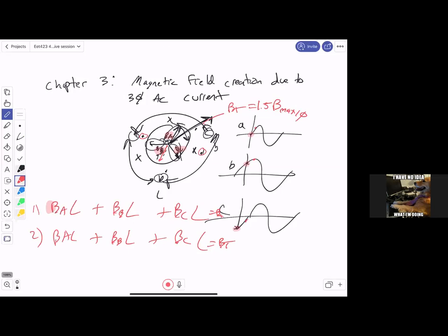Because I can't decouple whatever the device is connected to. The motor is connected to this external mechanical device, and I can't decouple it easily. Can you tell me how to wire this thing up? I see that this is 1, 2, 3, and I can see inside the machine how it goes. You would have to tell them, okay, take phase A to this point, take B to this one, and C to this one, based on the fact that you can't decouple it. So a practical application is you can't just decouple it and test it. You actually have to get it right the first time.